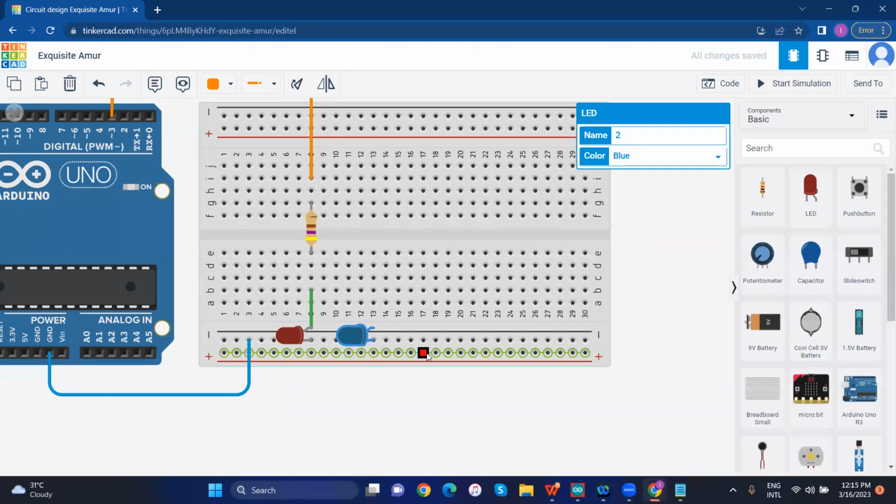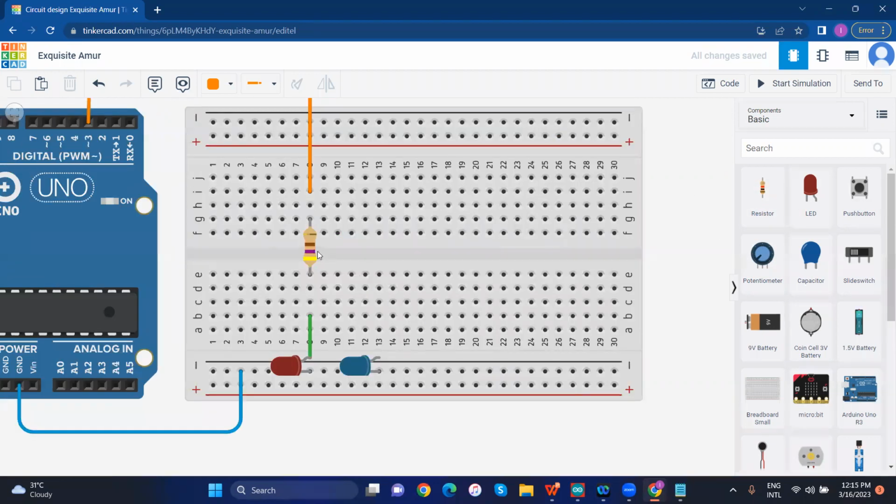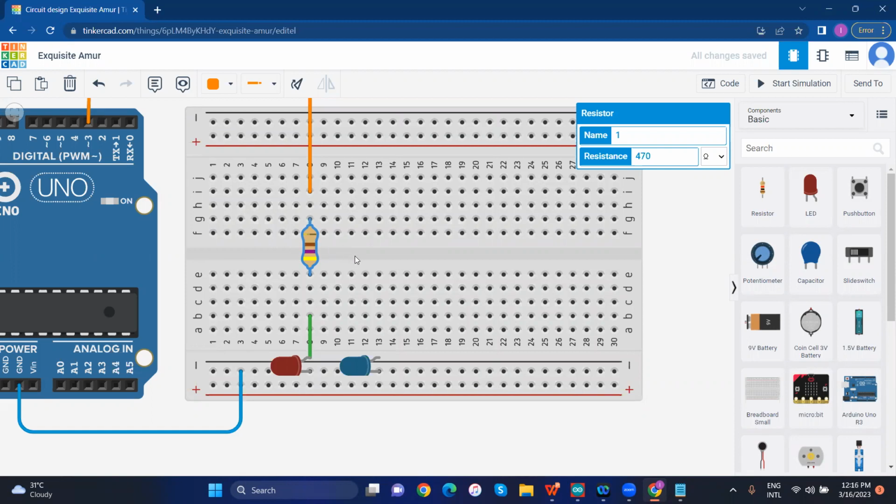Before connecting that LED, you should remove the USB connection. Remove the connection from the USB port and then connect the LED. Otherwise, if it is short circuited, then it gets some troubles. Like that you can connect. And you can take another resistor, same type, and connect the second resistor also, same as the previous one.